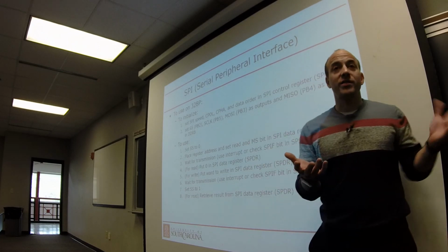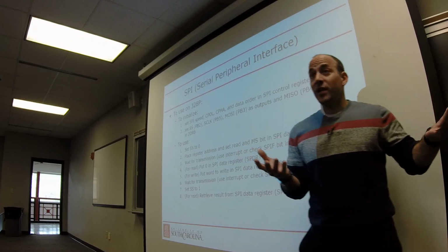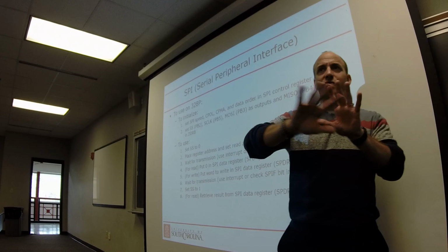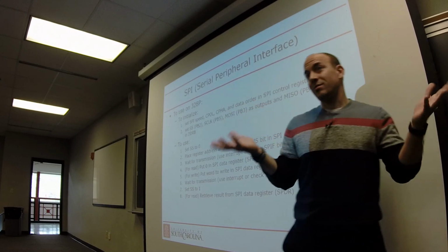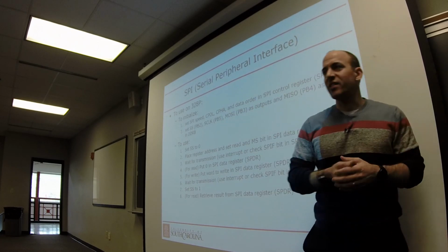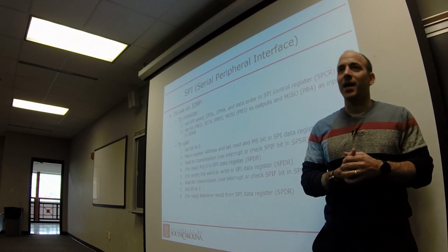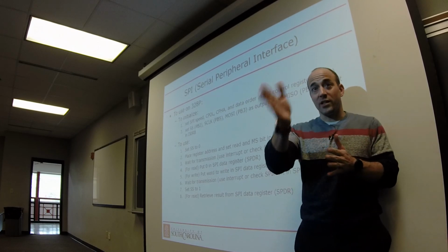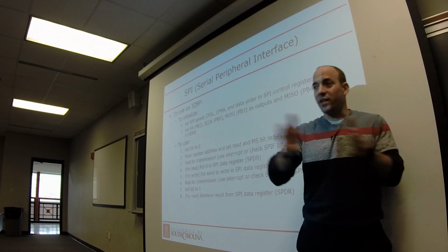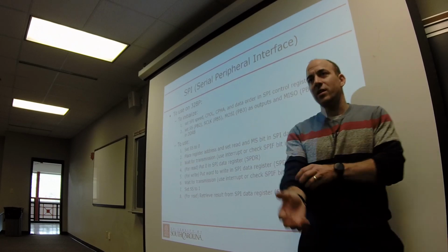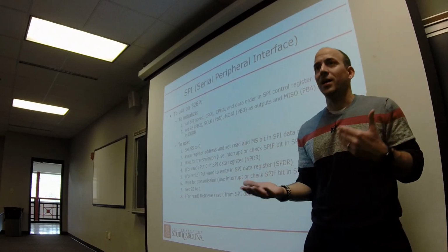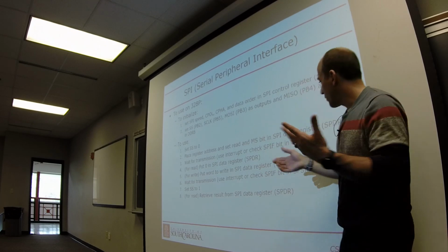And it's not like you can tell the SPI interface to send 1,000 bytes and you'll wait. No, it's not that smart. It's not like a DMA engine where you give it a starting address and a length and have it go in the background. It requires attention after every byte. So you could just wait.